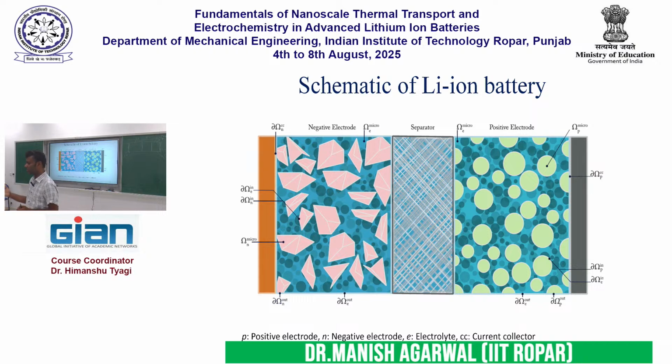The negative electrode is typically made of graphite, C6, and again there are some binders and other things to keep it together. Again, this is also a porous domain, so here also electrolyte is present. Then we have the current collector. Summarizing, everything is porous, and everywhere the electrolyte is present, whether in the electrode region or the separator region. You have the active particle, and you have the graphite here.